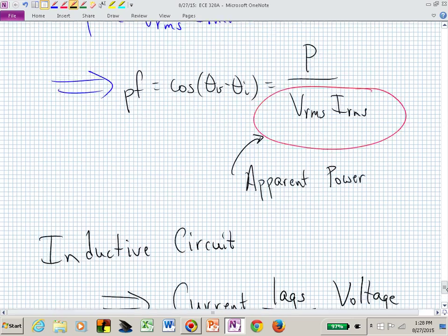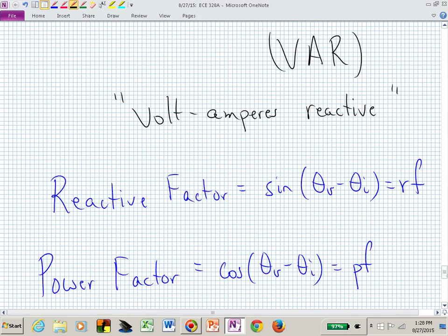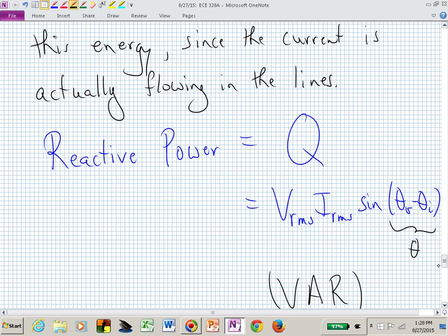And if that angle is positive, if this is how we've defined our reactive power Q, what do we know about the sign of capital Q? If that angle, theta, is positive, what's the sign of a positive angle? Positive. So if we have an inductive load, our Q, the reactive component of our power, is positive. Q is going to be going vertically up.